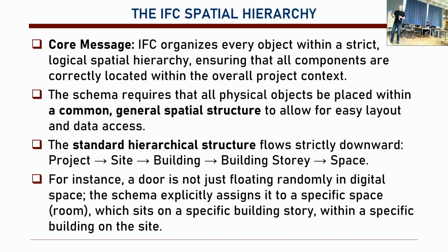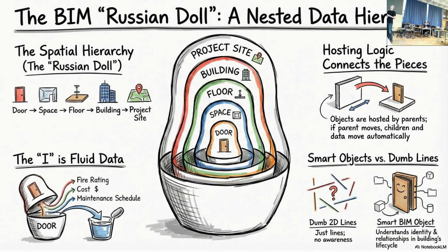But yeah, with BIM we have this hierarchy. So yeah, the door is in a room. It's in a building story. It's in a building on a site. Yes. Do we have any different site properties? Yes. There is a project management tab. There you define the project owner, the site, the location, etc. So it's defined. You can do that. So, just like a Russian doll, okay? Project, site, building, floor, space, and the element is in that space. Door, okay? So that is the idea.